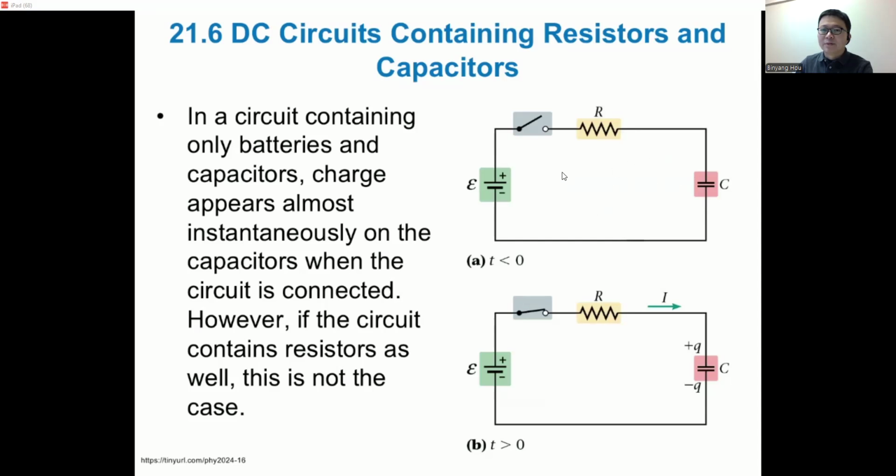And the same thing for the charge as well will increase and then flatten out. Okay, so because charge and voltage are proportional to each other. Remember when we do Q over V, it should give you the capacitance, right? So C equals Q over V, and C is a constant number, so Q and V should be proportional to each other. Okay, so that's what happens when you close the switch. So this process is called the charging of the capacitor. All right,